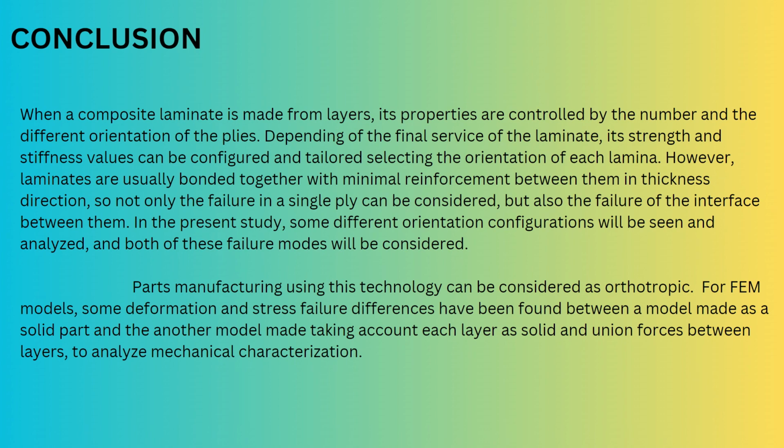In the present study, some different orientation configurations will be seen and analyzed, and both failure modes will be considered. Parts manufactured using this technology can be considered as orthotropic for FEM, or finite element, models. Some deformation and stress failure differences have been found between a model made as a solid part and another model made taking each layer as solid, with union forces between layers, to analyze the mechanical characterization.